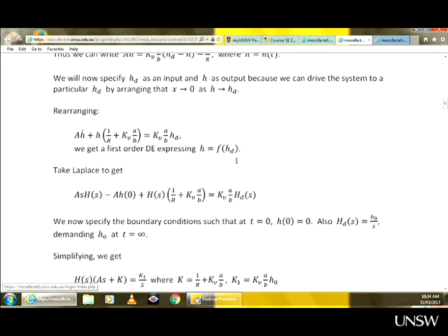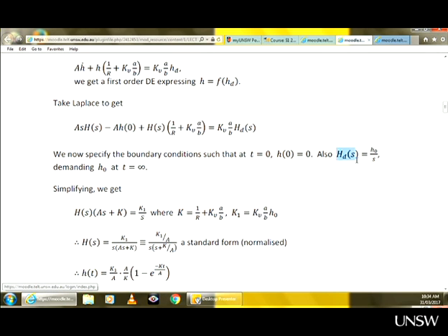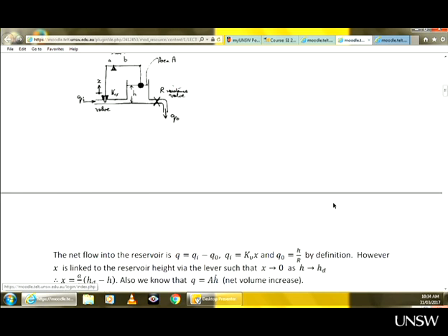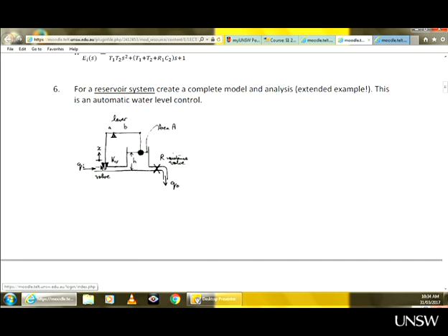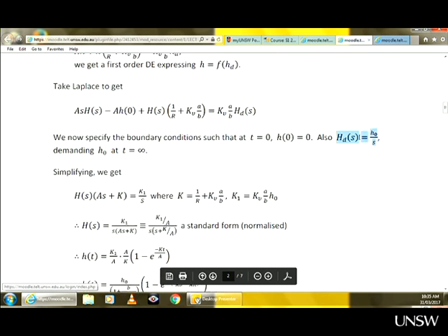Okay. What follows is pretty well known. Laplace transform, assume zero initial conditions, and we are going to assume also that the desired value is applied in the form of a step. It is very hard to show in this system where you actually apply it. So we can imagine it is this valve that maybe you tighten a screw or loosen the screw, and you do it quickly enough to assume that it resembles a step function. Okay, so the desired value is a step function, and H0 is the desired value of the height, so what we want to achieve.